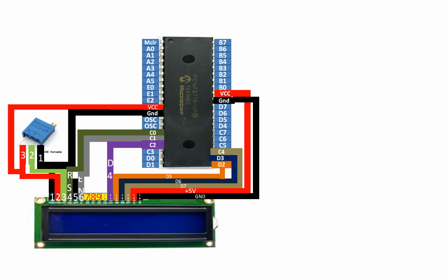We are going to use this LCD in the 4-bit mode. If you want to use this LCD in the 8-bit mode, only then you are going to need these 4 pins. Now guys, this over here is our push button, and let me label the 2 pins as left one as L and right one as VCC. Here you can shuffle these 2 pins, like you can take the left one as the VCC, right one as L.